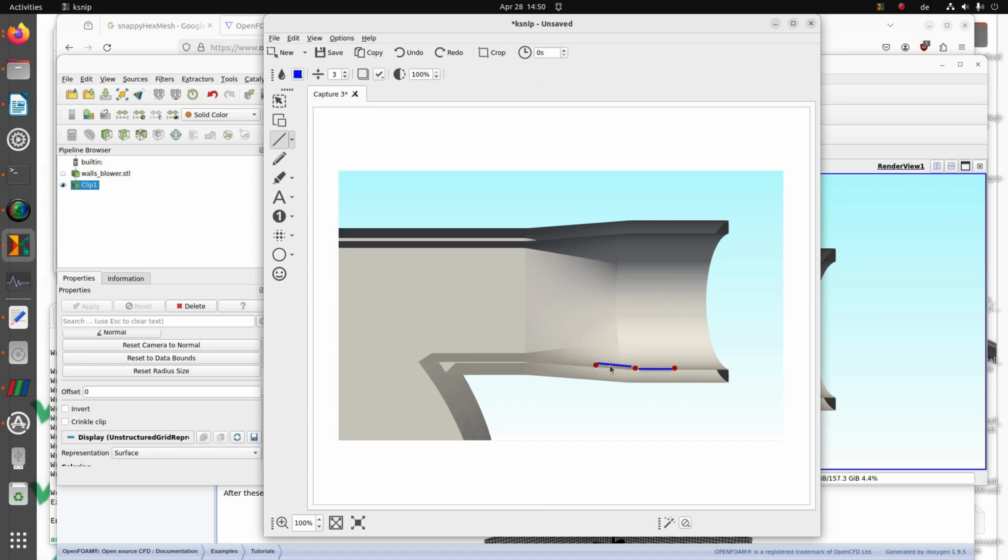We have edge length is blue, and the distance is the factor times this maximum edge length. If your edge refinement defined as 32, for example, as it is in this case, then the snapControl will take 1 point, for example the middle one, and set the next point during the snap process around 32 millimeter radius from this point. Also all points in radius of 32 millimeters.